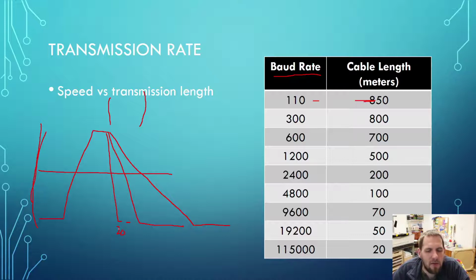All right, so that diagonal, that time it takes to change from a high to a low, is going to be affected because your computer is going to send a signal, hey, transition, and it's going to go, okay, I'm going to transition, and it's going to try to. But because of the length of the wire and the capacitance that it's created, it is going to take longer and longer for it to actually make that transition, which is why we can only send things at a much, much, much lower rate.